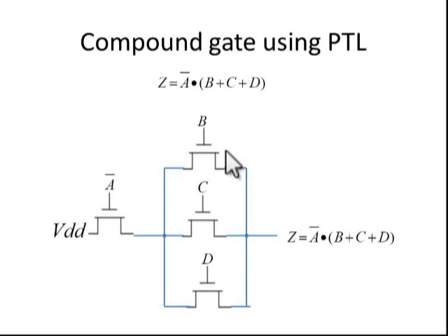So usually if the condition is failed, it should give 0. Am I correct? When the condition is satisfied, Z should be 1. If the condition is failed, Z should be 0. So here we are expecting Z should be 0, but here Z won't be 0. It will retain the previous value, that is the output doesn't go to 0.